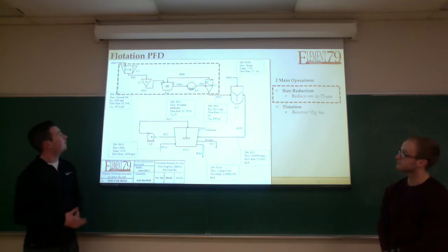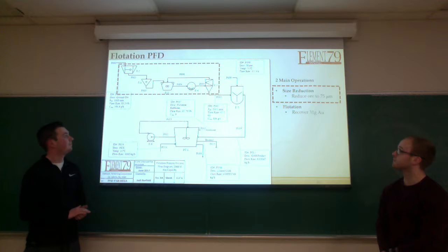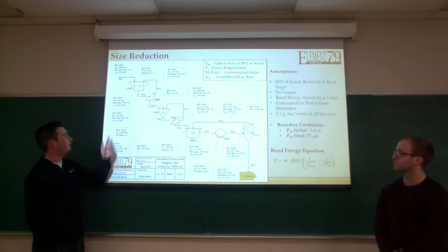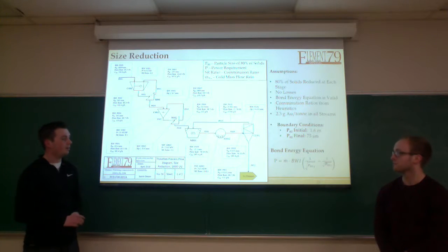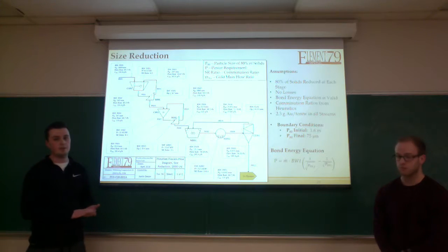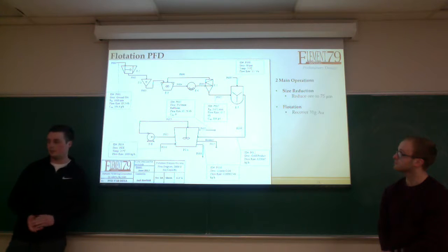Right here is our flotation PFD, so I'm going to go a little more into the size reduction area. This is our size reduction PFD. As you can see, we have our primary crushing and secondary crushing, which is followed by our ball mill and our SAG mill, and finally our hydrocyclone that goes on to flotation. Now Justin's going to take you through the flotation section.